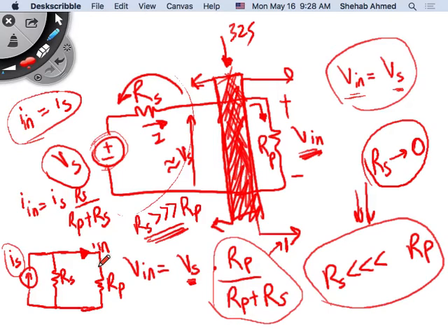We will find that if you have an input impedance to any circuit that is 0, what does that mean? That if I put a voltage source at that input, this is modeled as a short circuit. If it's a short circuit, then current will be flowing here.